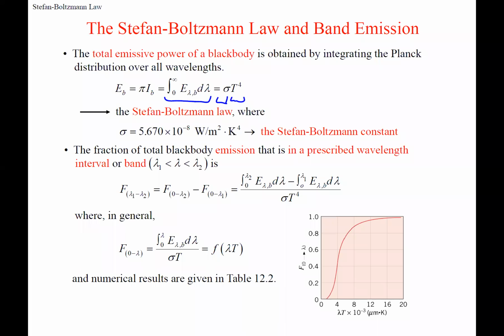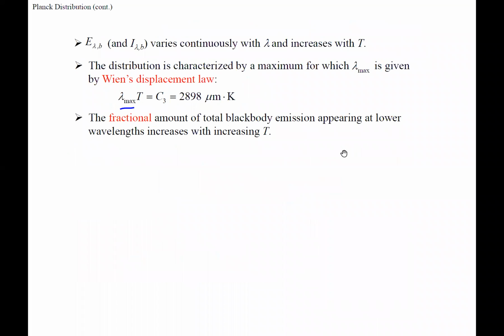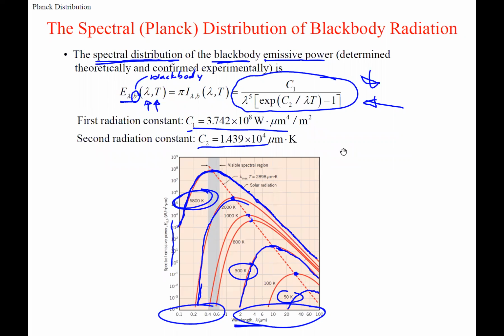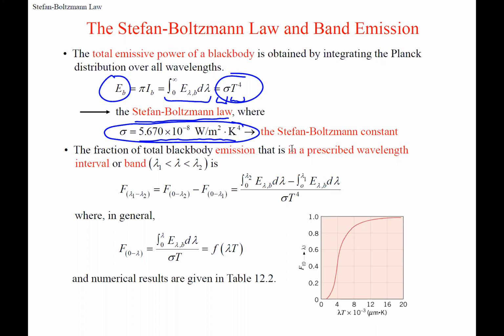That's the equation we've been using, and that's where it comes from. This Stefan-Boltzmann law is where the Stefan-Boltzmann constant we've been using comes from. It comes from that integration of this equation, leaving the temperature influence in there and integrating everything else out over all those wavelengths.